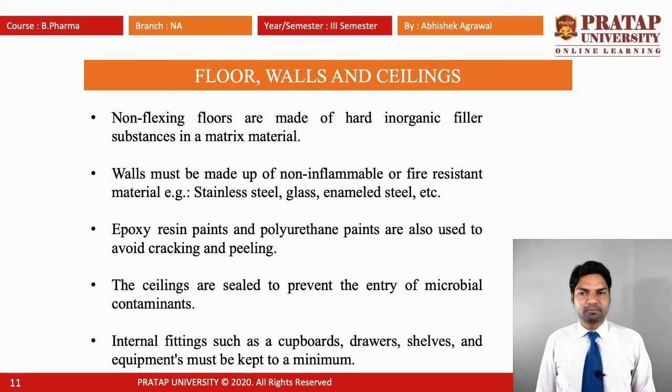The non-flexing floors. The non-flexing floors are made up of hard inorganic filler substance in a matrix material. The wall must be made up of non-inflammable or fire resistant material such as stainless steel, glass and enameled steel. The epoxy resin paints and polyurethane paints are also used to avoid cracking and peeling.